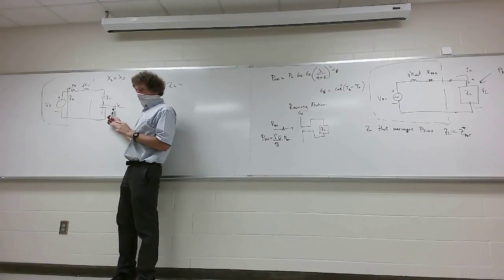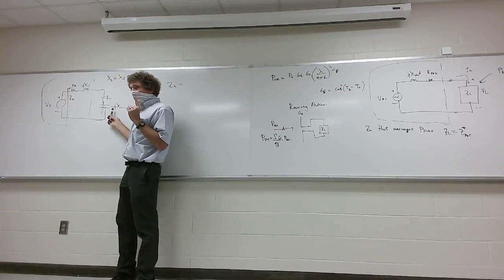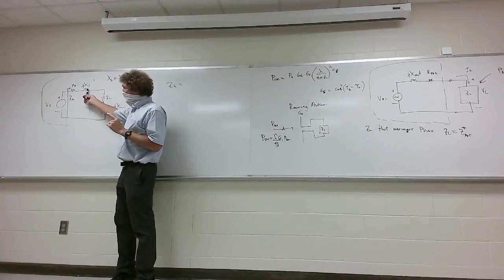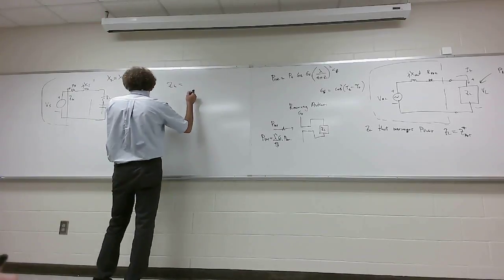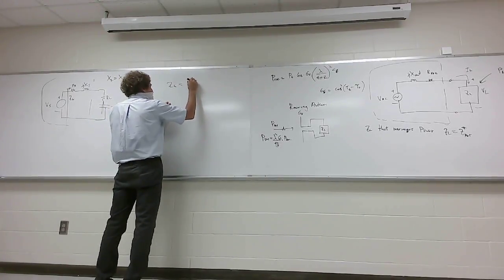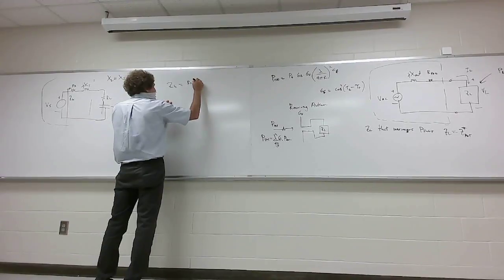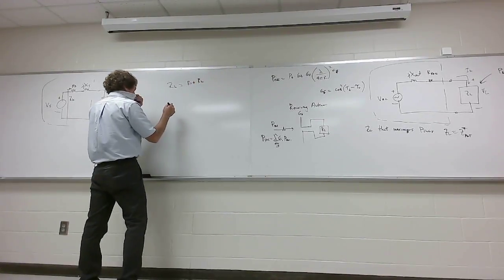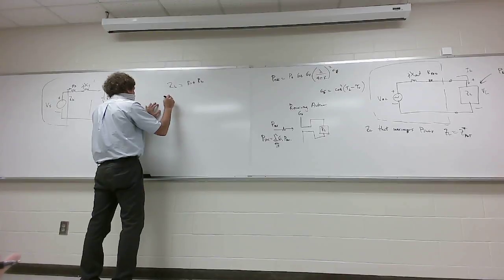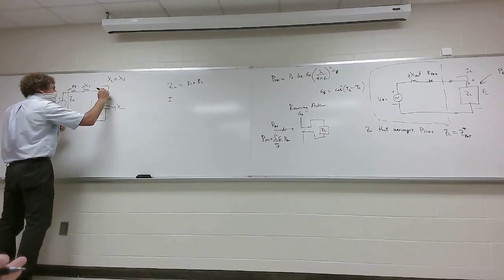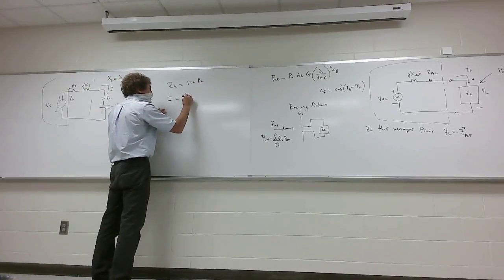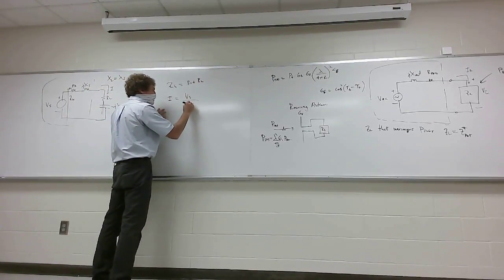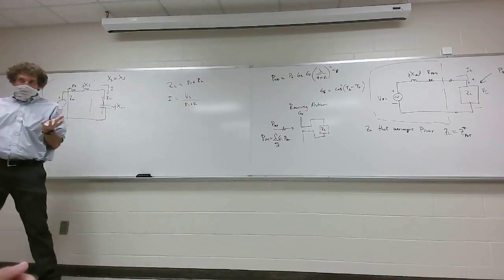And then it's minus JXL, right? Now you can sort of see if I make this impedance exactly the same in magnitude and opposite in phase as that one, they cancel. Do y'all got me on that? That's the reason. So Z total would just be RS plus RL. Now if I have that, the current I that would be flowing here would be Vs over Rs plus RL, right? Y'all agree with that?